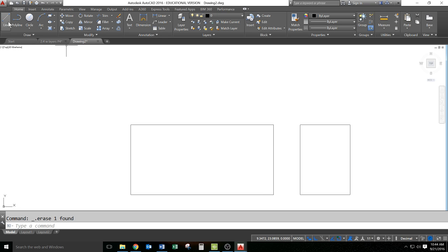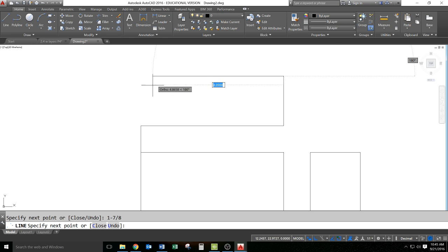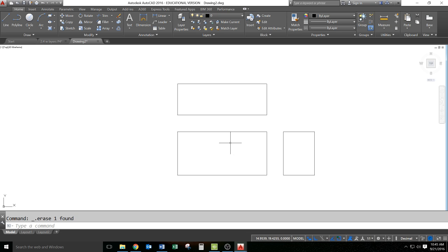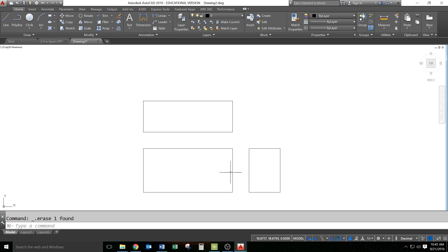I'll do the same thing for the top. I'll draw a 1 inch line right here, so 1, enter. I'll draw a line straight over, goes here because these have the same width, and then it also has the same depth of 1 7/8, so 1-7 divided by 8. Come back over here, put my mouse right there for a second, click, click, and close, and now I can delete this space saver. Okay, so there's my front view here, here's my right view, here's my top view.